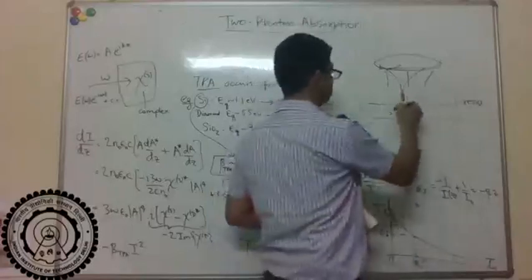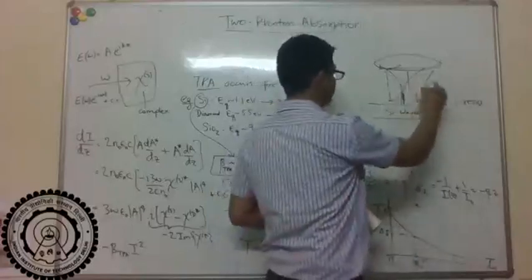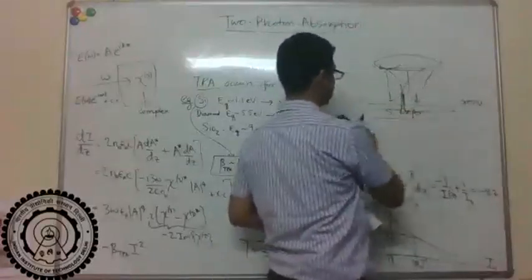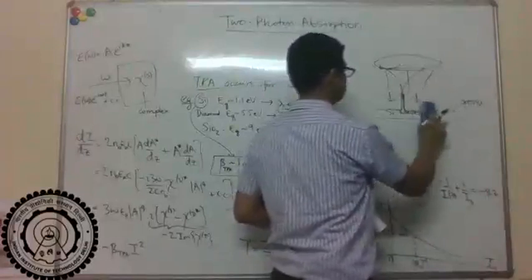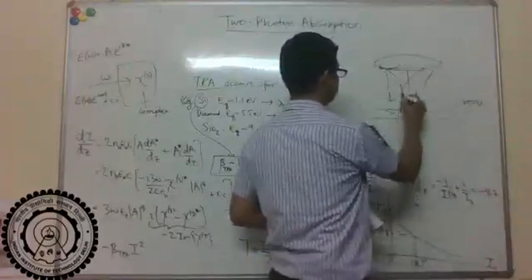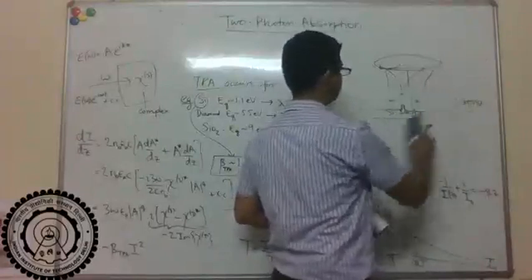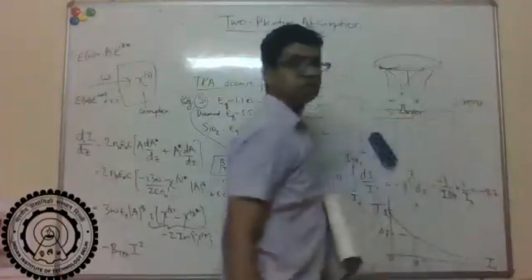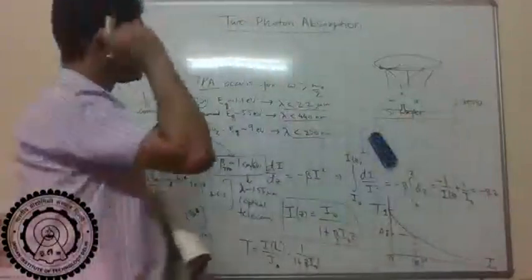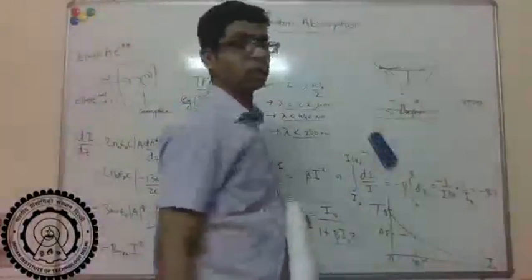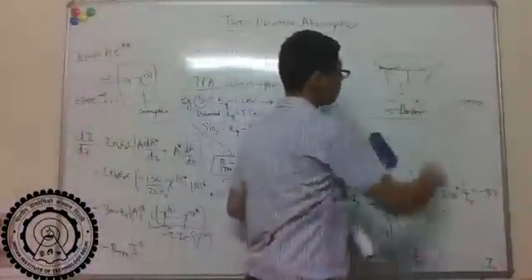And then you can do further processing like etching. So only this part will be etched, right? The part which has the resist on top will not be etched, and then you finally remove this resist. So you end up with some waveguide-like structure on your silicon, right? So that's how photonic and electronic components are made, and so this process is called lithography.